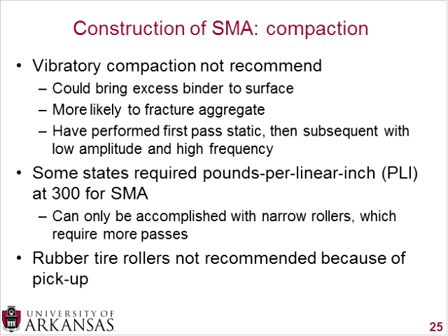And we've been talking quite a bit about compaction here, and there's good reason for that. Like I said, you want to get it compacted as quickly as possible because of the open nature of the mix. Air can get into the mix, it can start cooling quickly, and if you don't get that compaction down, then you won't get the densities that you have designed for.